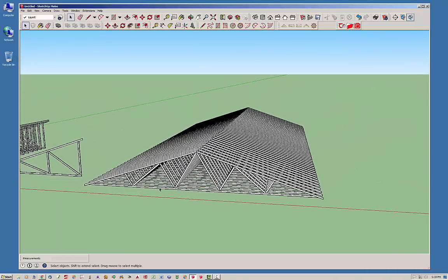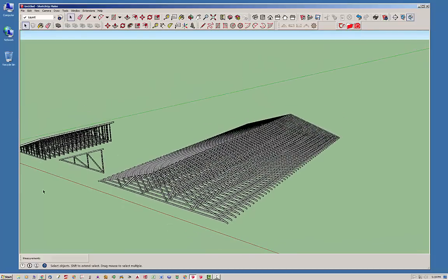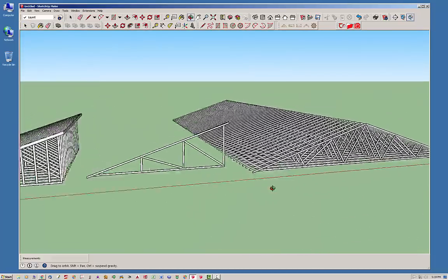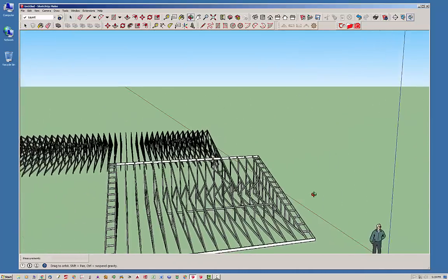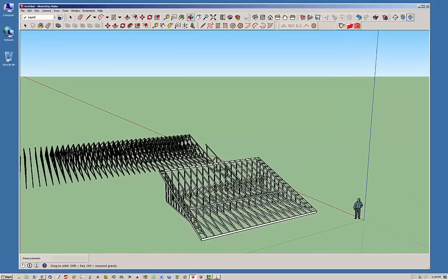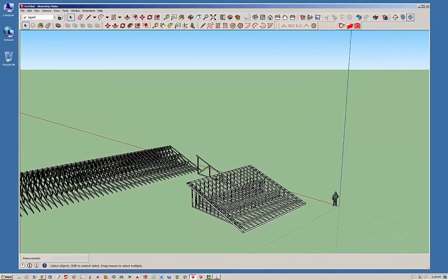Basically, if the length between these panel points, as they're called, gets above about 10 to 12 feet in general, it gets too long and you have to use more webs. So anyways, I think that's probably pretty good for now. Next time we'll go into making floor trusses and floor joists and that sort of thing.